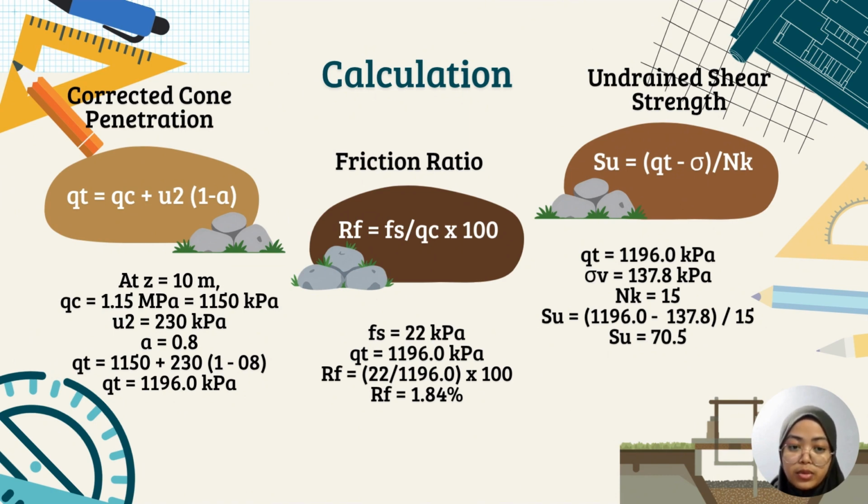Based on the CPTU parameters, the site consists of organic peat crust in the upper layer, followed by clay and silty clay, and finally a stronger silty clay or clayey silt layer at deeper depths. In conclusion, the CPTU results show that the site contains weak organic clay and soft clay in upper layers, which have low strength and high compressibility.